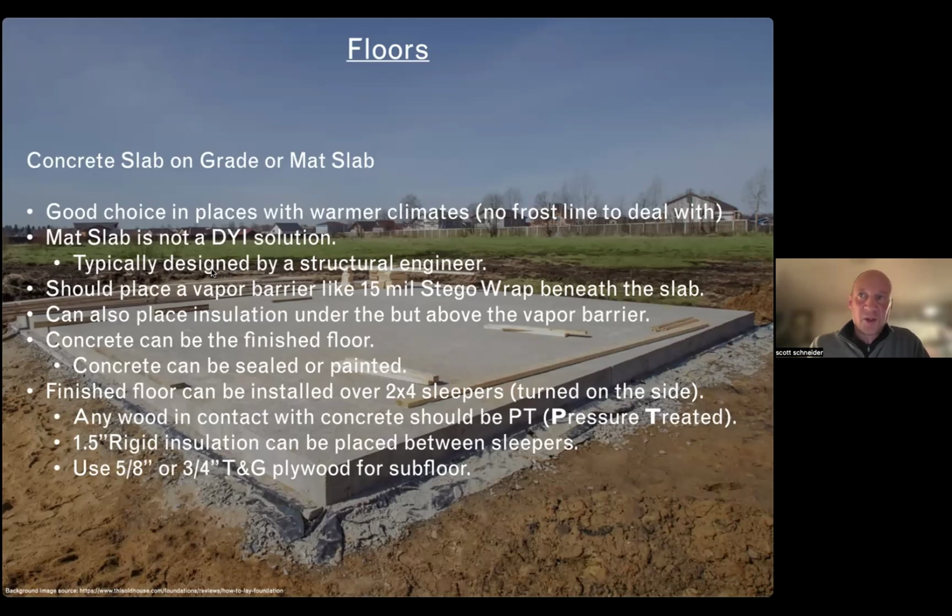They start at around 12 inches deep and can go to like 18, depending on what type of loads there may be on the slab. And for telescopes, you're going to want something a little bit thicker, heavier, with more rebar, for if you're drilling in multiple piers. There may also be people walking on it at certain times, and you don't want to disrupt the observing.